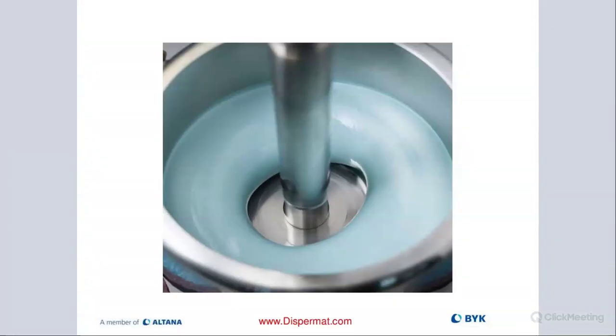Okay, the donut is obviously the visual cue, always nice to see when we're pre-dispersing. Here we can already see a really beautiful donut. The center of the blade is exposed, and right around it, where the edge of the blade and the teeth are, that's where we can see the donut being formed.